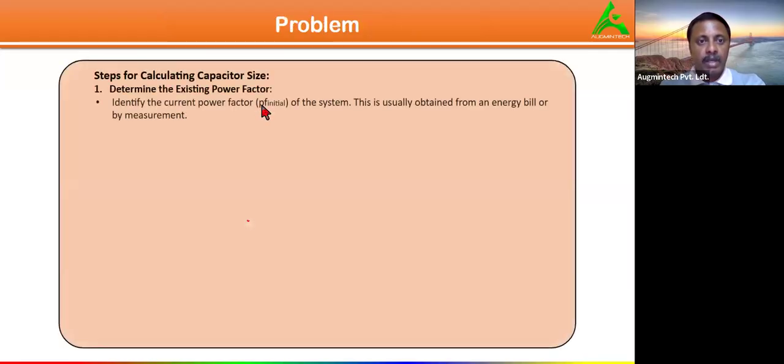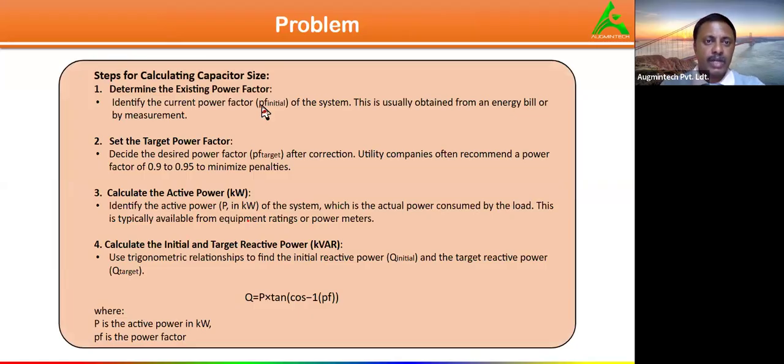And this is a simple thing, in order to calculate the capacitor bank, nothing much. Just a sample example, you can see this. If we know the real power, that's it, we can calculate the reactive power. I think I showed you in one of the load calculations, a load schedule, where we have seen this. The first thing is you have to determine the existing power factor. Usually there will be a power factor meter in your industry or building, wherever it is, along the LT panels.